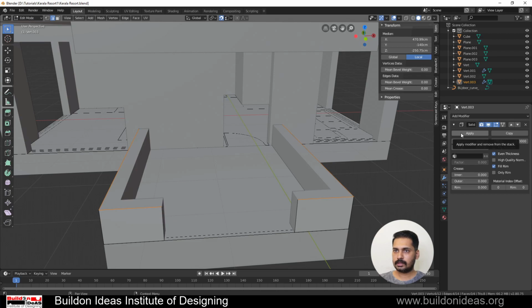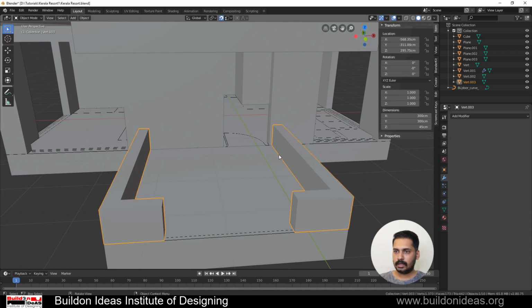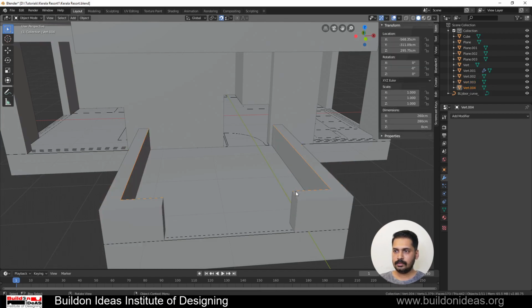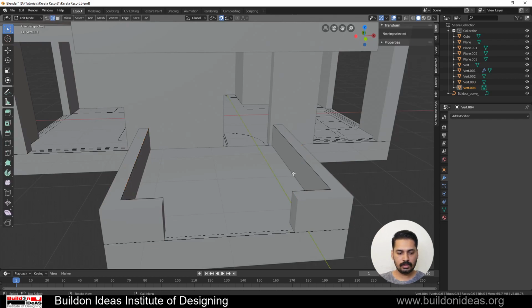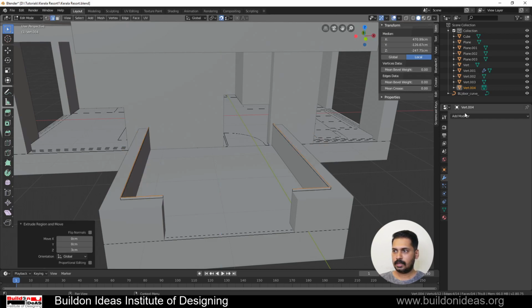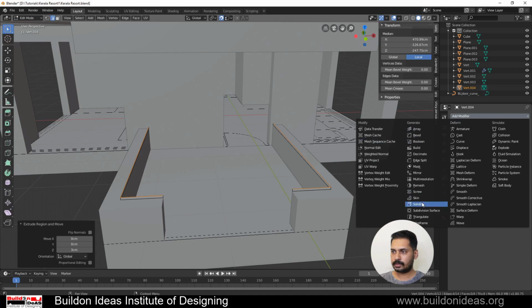First of all, I'm just applying it in object mode, and then I'm selecting these 2 edges and these 2 edges once again, and then I'm going Shift D and then Escape and then P to separate these from the other. Then I'm giving an extrude: going into edit mode, edge mode, A, and then extrude by say Z direction 3 centimeters just to have the thickness,